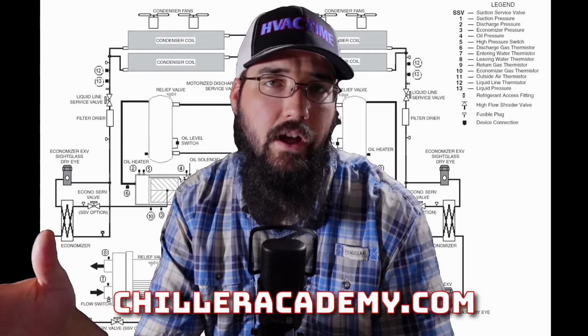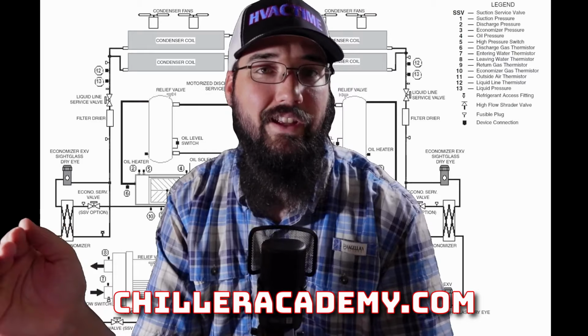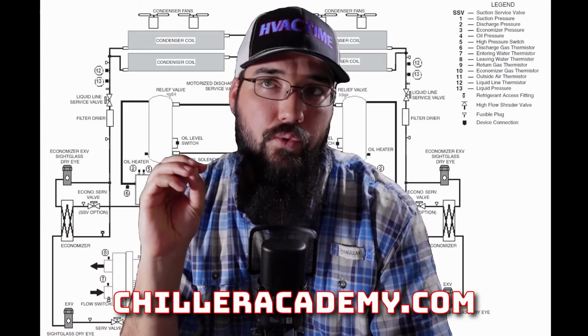If we're starting to run high head pressure for whatever reason, dirty coils, bad fans, non-condensables, whatever, then we're going to limit how much the compressor can stage up, and it won't let it go past that. Now, moving into current limit.